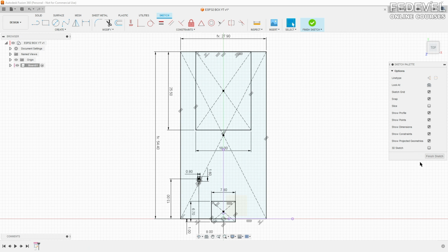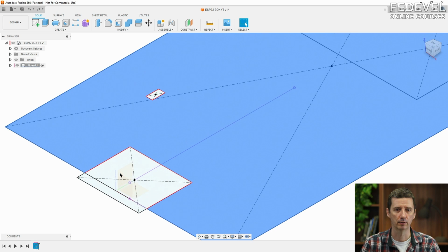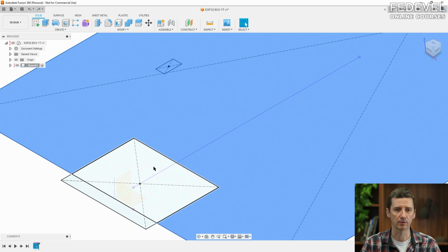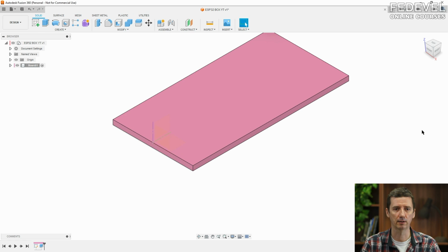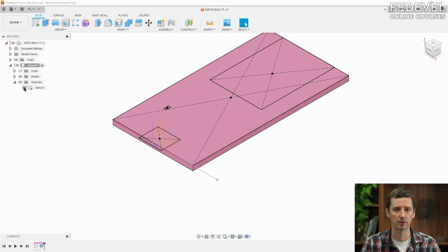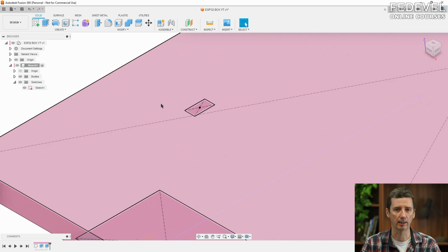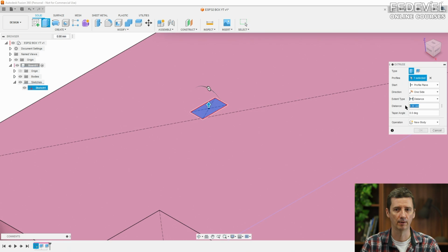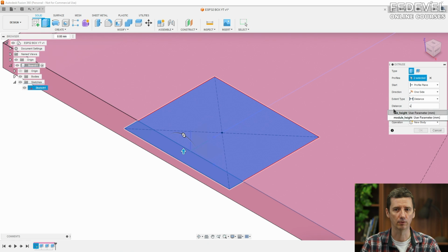Okay. Finish the sketch. Go to default view. We are going to create the PCB. So select all these. Use this feature, put here PCB thickness, minus PCB thickness. Okay. Make the sketch visible. We would like to draw the model of the module and also add LED. Just specify the height of the LED.